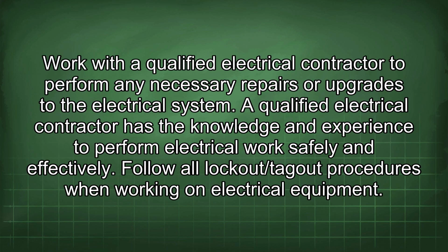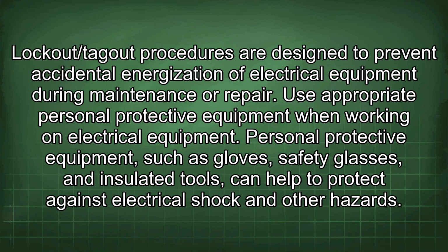Work with a qualified electrical contractor to perform any necessary repairs or upgrades to the electrical system. A qualified electrical contractor has the knowledge and experience to perform electrical work safely and effectively. Follow all lockout/tagout procedures when working on electrical equipment. Lockout/tagout procedures are designed to prevent accidental energization of electrical equipment during maintenance or repair.